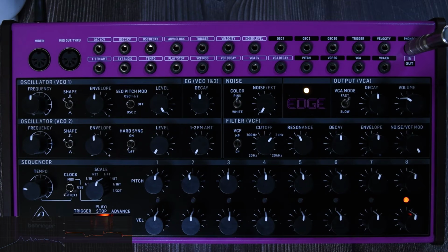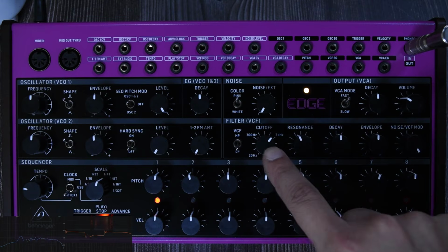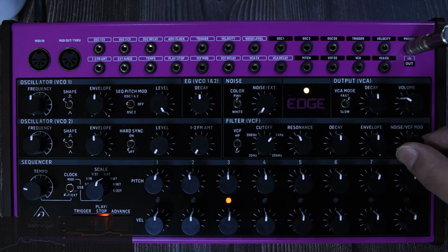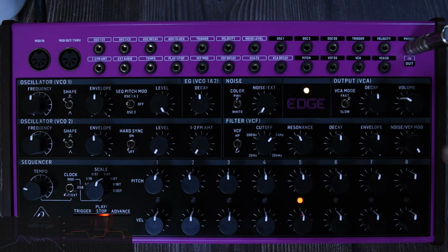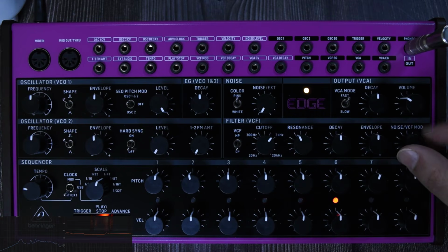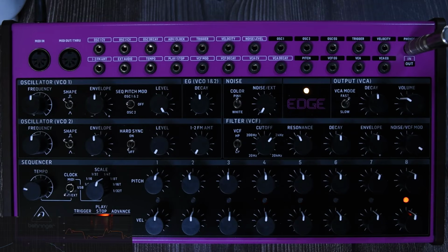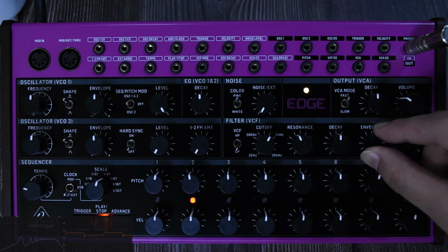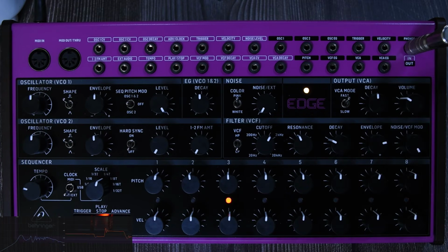It uses the noise generator that we have right here to modulate the cutoff. That's why we get this noisy sound. It's modulating the cutoff super fast. This is what the noise means. But then it says VCF Mod. And it's because with using the patch bay, we can disconnect or remove the noise as a modulator to the cutoff and use maybe something else. And that's going to be the VCF Mod side. But by default, this is hardwired to use noise as a modulation source. Now, still, when you modulate with noise, you can modulate with envelope if you desire.